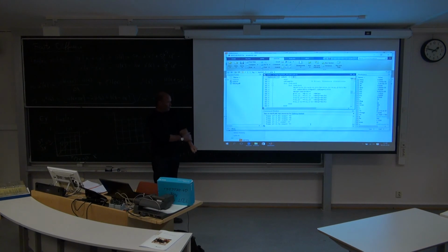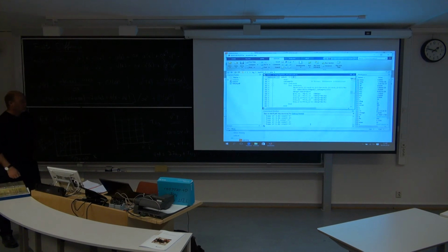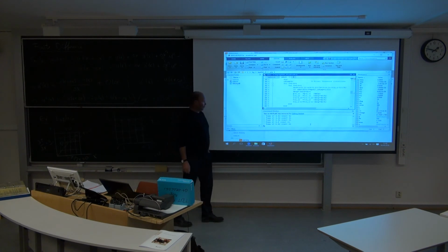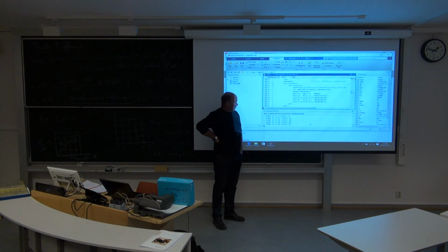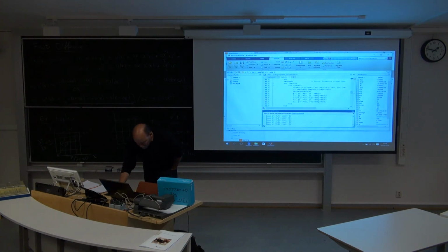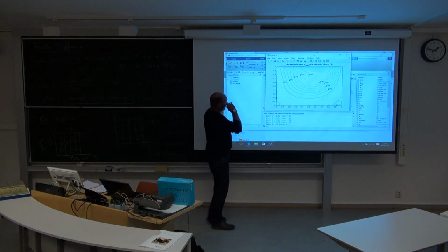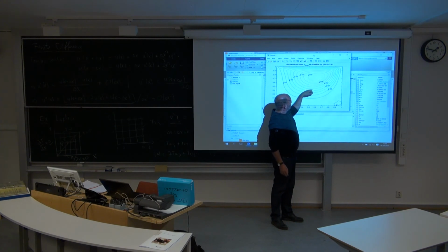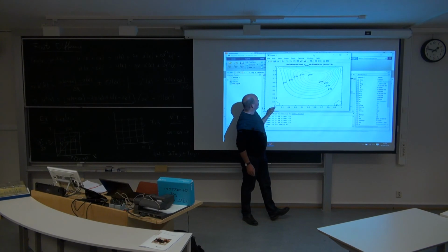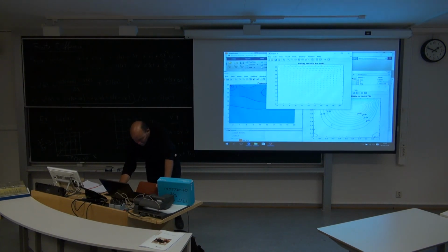So just to show you, if you have forgotten what this SOLA problem was, it was not this temperature problem, it was a square cavity test case. So 3 walls standing still, top wall starts to move at constant velocity at time equals 0, and then we will get one big primary vortex inside our cavity and some secondary vortices as well. Let's see if we can get it now. Here we have the streamlines and the stream function close to 0.1 in the center now. One big vortex, secondary vortex, and we even have pressure, and we also have the velocity contour. So this is the square cavity.